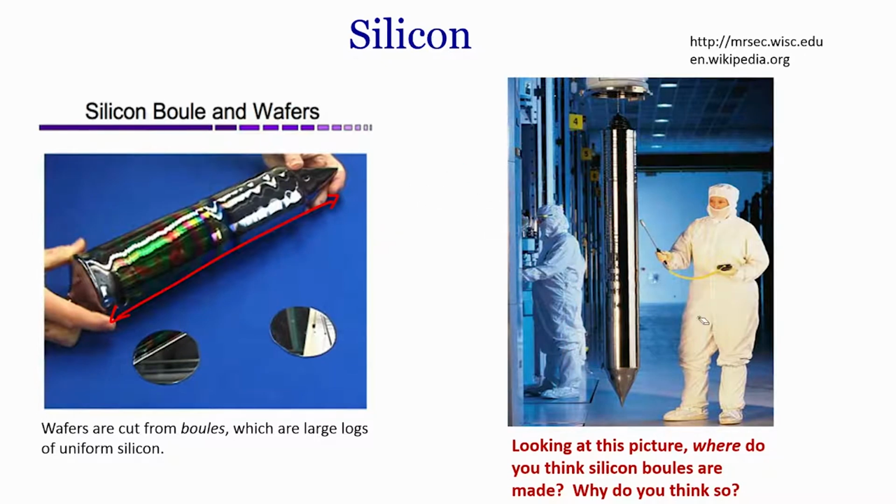We are talking about a few nanometers of technology, where you fabricate MOSFETs, metal oxide semiconductor field effect transistors. If a 0.5 micron particle sits on the wafer, it will kill thousands of transistors at the same time. To avoid that, we require a clean room facility.